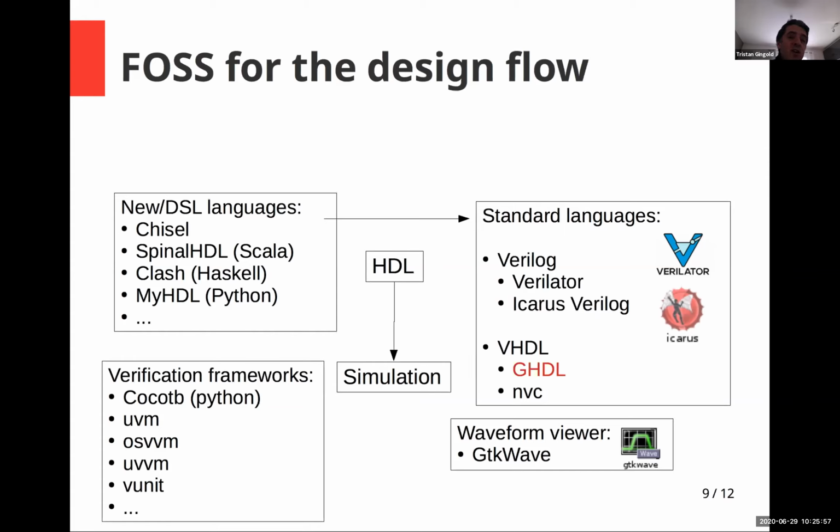These languages allow you to write maybe more flexible code and more dense code. But in order to do a real chip at the end, all of them need to convert the code into either Verilog or VHDL code in order to go into the design flow.